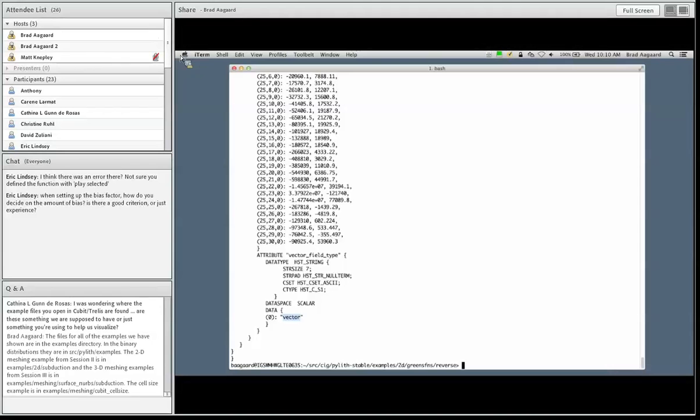So let's walk through that. We're going to call our Python script. We have our impulses file, which is computed using Green's functions. That's what our impulses are, so that's the fault output file. Our responses are the Green's functions points. That's our displacements at those points for each of those impulses.